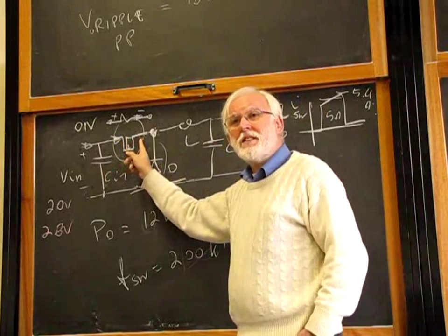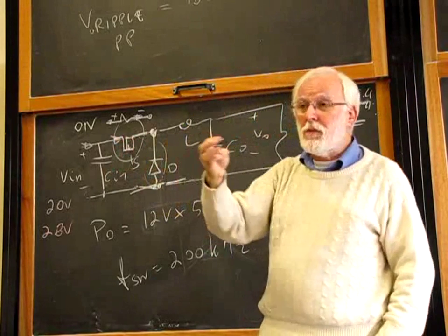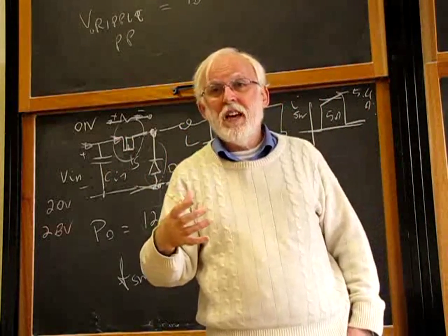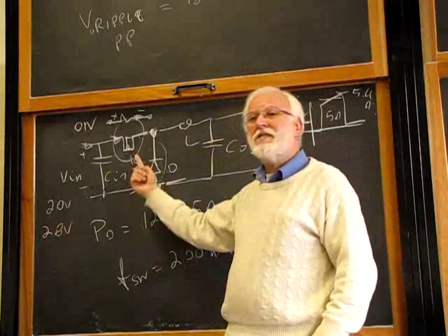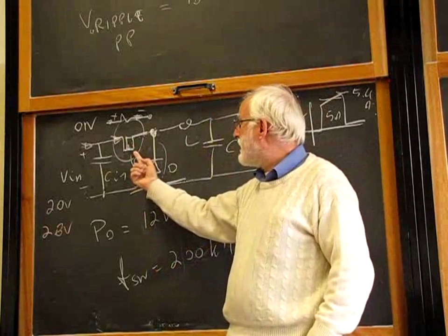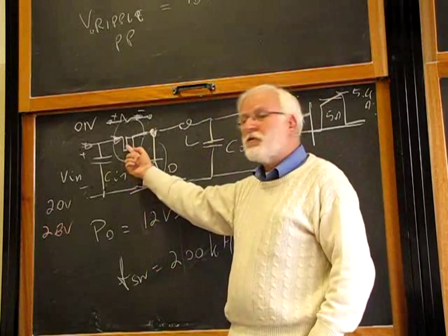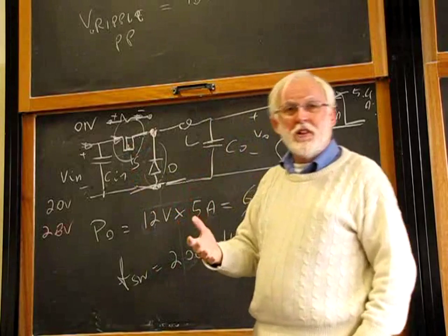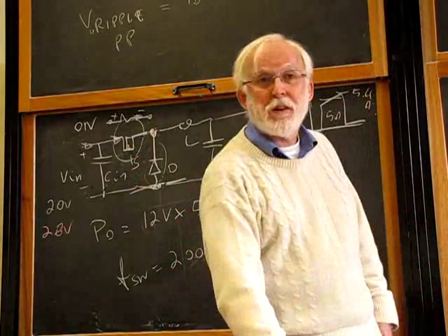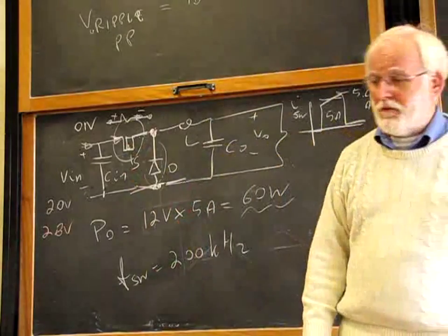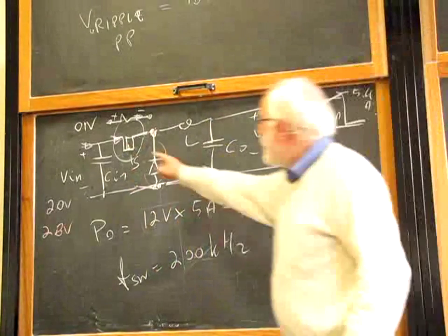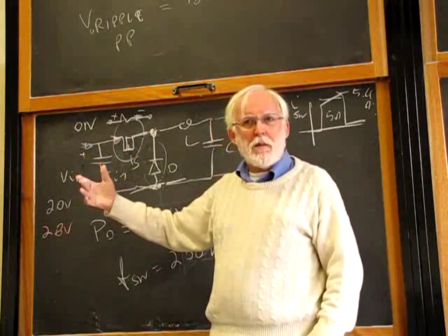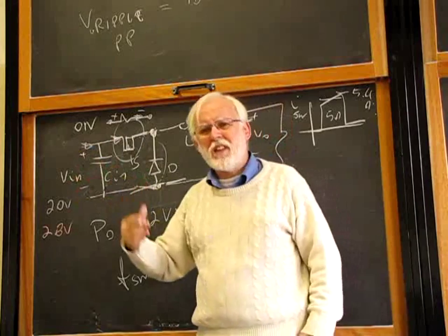Choosing a very large component requires a lot of money, because a large component means more expensive, and it requires a very strong driving circuit, because in order to drive a large capacitance, you need to provide a lot of current. So don't overkill your problem. If you overkill your problem, usually it's wrong, because you pay too much. A voltage drop in the order of a few percent of the input voltage is probably acceptable, except in very rare cases.